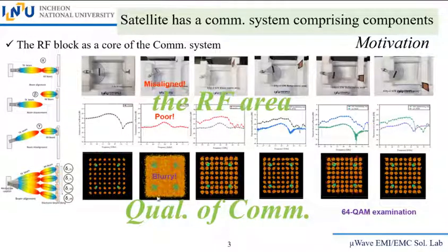So except this, this antenna was moved from the central location on the bar to the right-hand side. Actually, it doesn't have the function of beam forming or beam steering. Then the beam from the receiving antenna sees the minus z direction, but the horn antenna sees, for example, 45 degrees from the horizontal axis. Then we judge that as misalignment between the two beams.